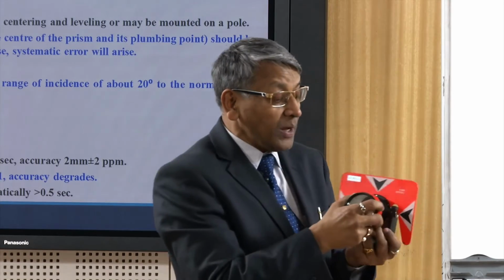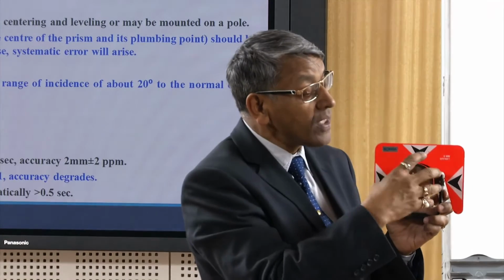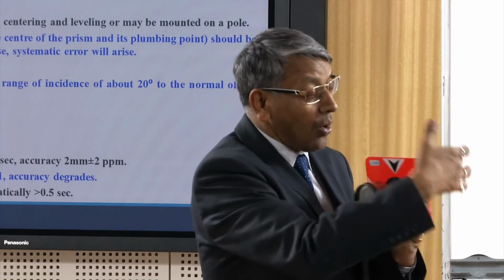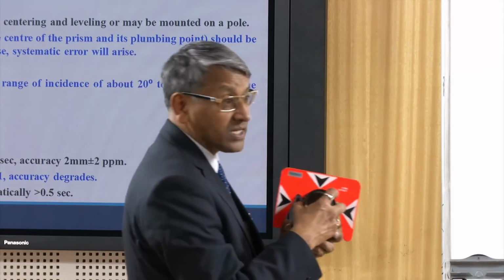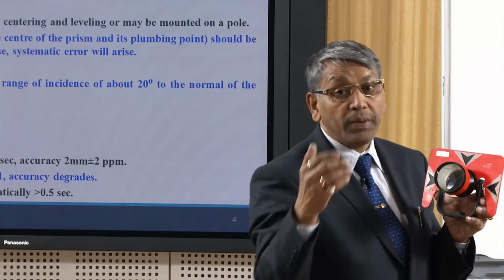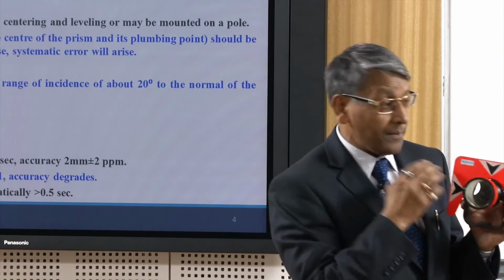So, we should be careful to see whether we are fixing our prism this end or that end. Accordingly, we have to take the prism constant into consideration, otherwise there will always be some systematic error in making use of the prism.